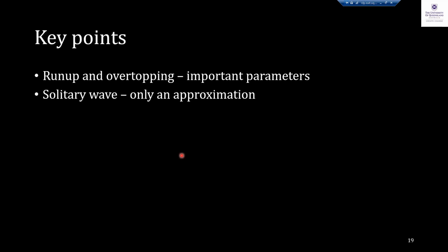So that was a background of tsunami research, what people have been focusing on. The key points are that run-up and overtopping are important parameters in designing structures. And use of a solitary wave is only an approximation to a tsunami wave, but not a true representation of a tsunami wave when we want to look at overtopping on beaches.